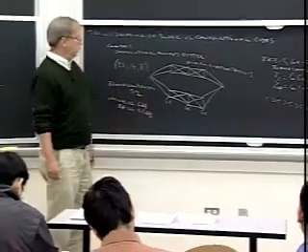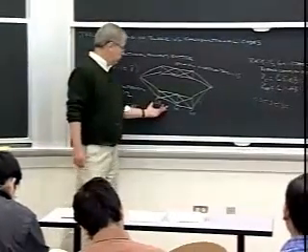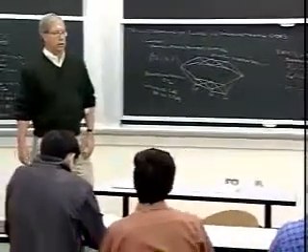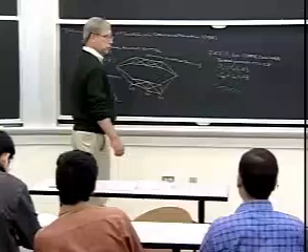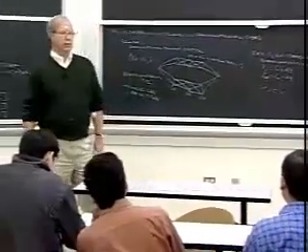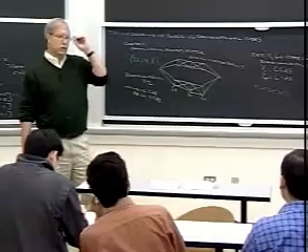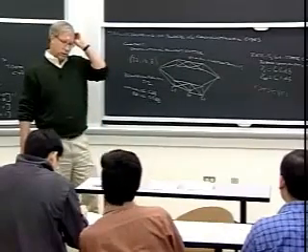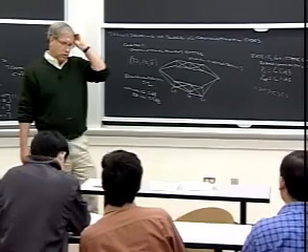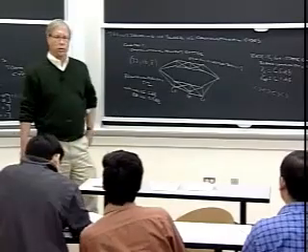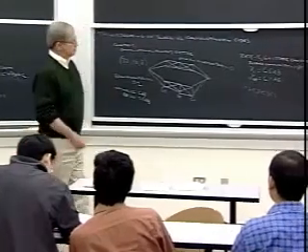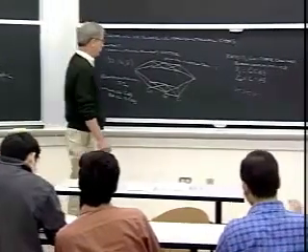It used to be that you thought of 64 states as a lot of states. But clearly technology has progressed, and now you wouldn't blink at 1,000 states, or maybe even 8,000 or 16,000 states. The biggest Viterbi decoder that was ever built had 2 to the 14th states, for the space program out of JPL. So anyway, it's doable now.